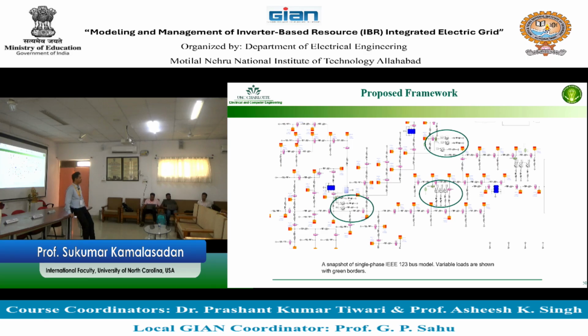What are the devices that you use to control the voltage in distribution system? Voltage regulators. Transformer is called OLTC. LTC or OLTC. What else?